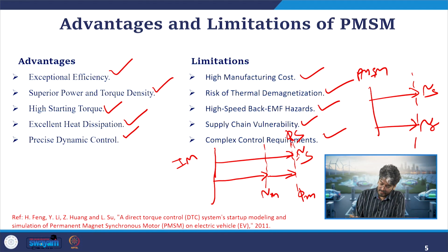So in our synchronous machine, as we have a permanent magnet on the rotor circuit, it should rotate at that particular speed such that the relative speed between both the fluxes becomes zero, and torque can be produced. So this is why we have some slip in the induction machine, and we do not have any concept of slip in the PMSM. It rotates at that particular speed.